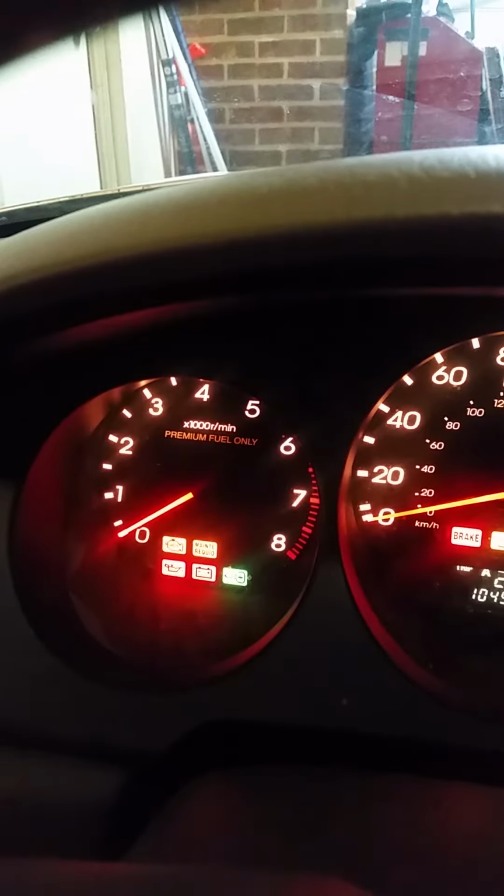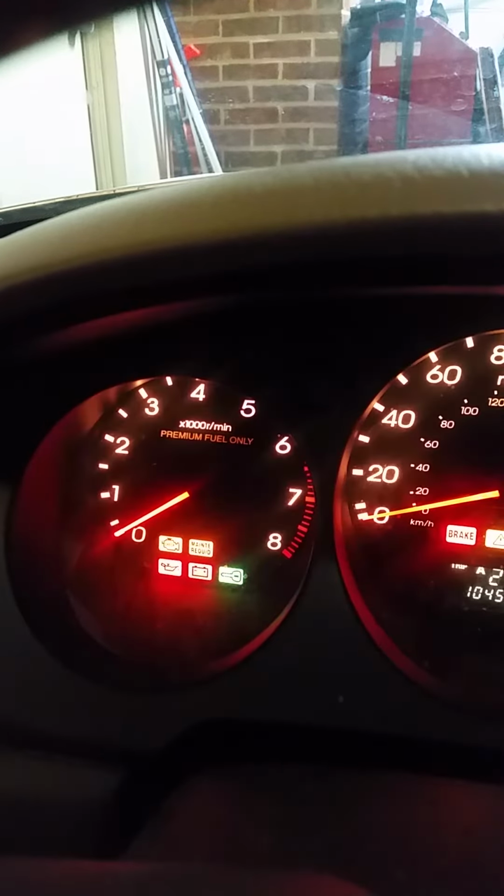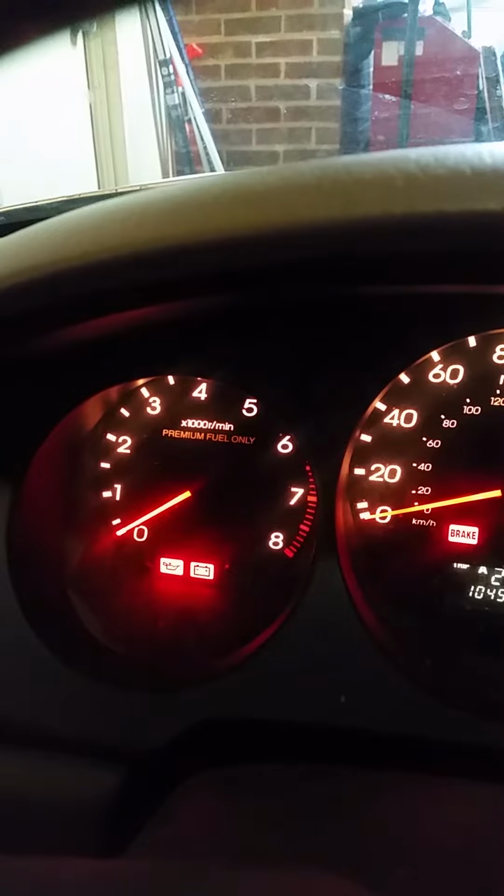They have a characteristic click, and hopefully you'll hear it. I'll put the camera down here somewhere. Hopefully you'll hear it. But when I turn on the ignition here, okay, if you can hear it, it'll actually click when the check engine light goes off. It's kind of simultaneous here. So I believe the check engine light's in this third dial gauge over here. Let's see. Don't know if you heard that. So the check engine light is top left. Click. All right, so that works.